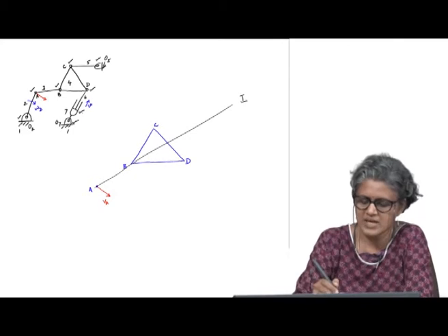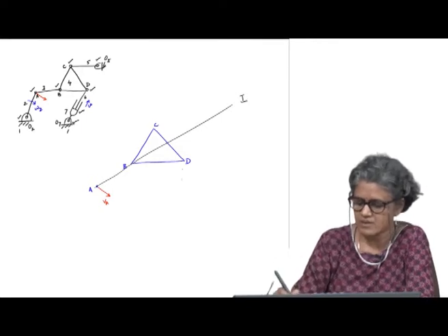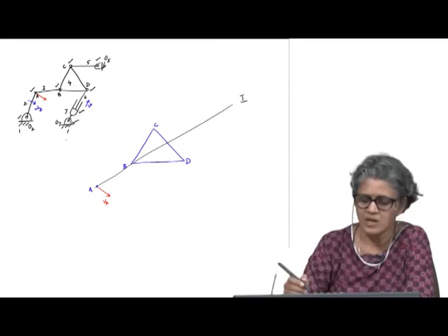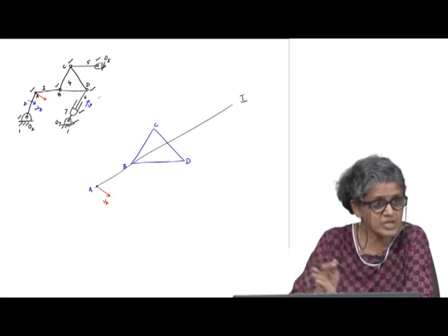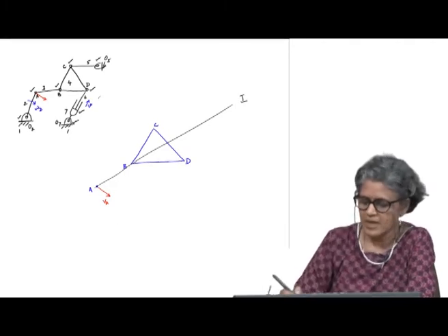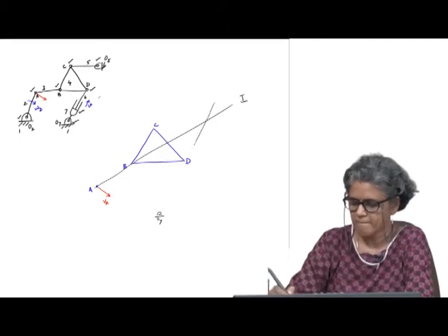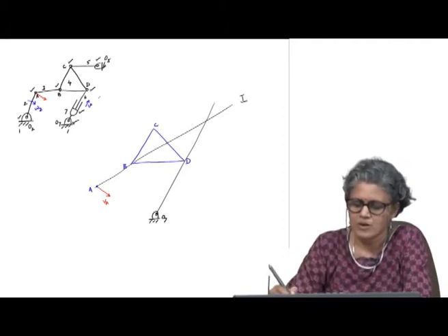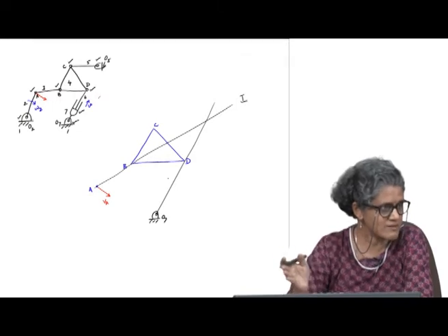Now, there is another velocity I know, which is this velocity here, and that is along this line O7D. So, the other component of the velocity is perpendicular to this, so that is not going to be transmitted. If I take an auxiliary line along this, say this is my O7, then I know the component of the velocity that is transmitted, because I know this velocity v.